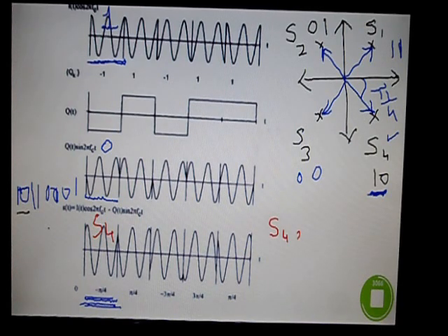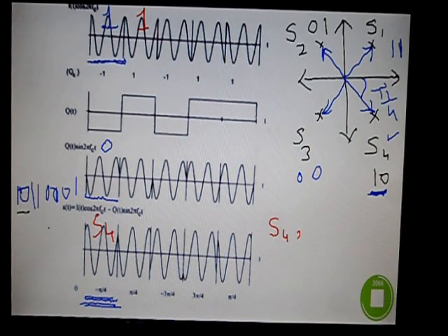Now, the second symbol. If you observe the data again, this data is for 1 in the second period, and this is also for 1, right? So 1 and 1, whenever you encounter 1 and 1 data, you would transmit S1. As can be seen in the constellation, you would transmit this S1 signal.